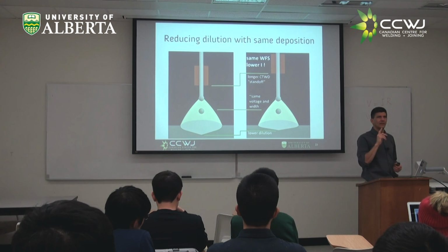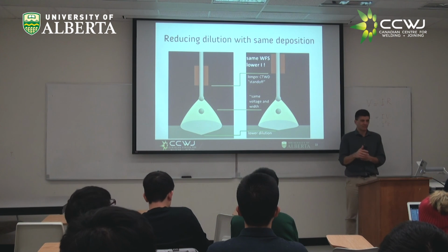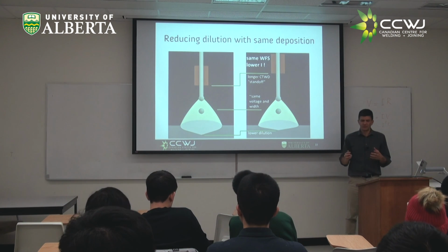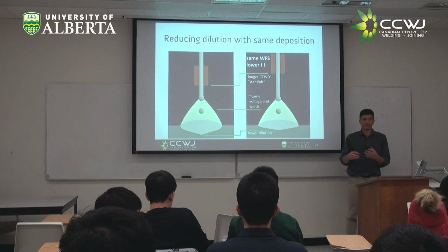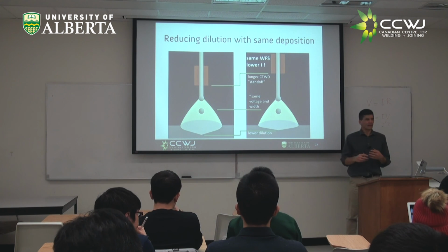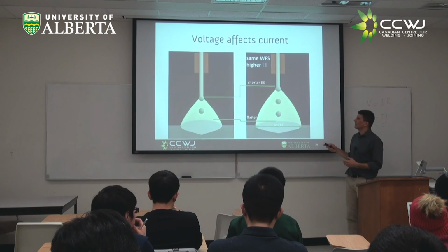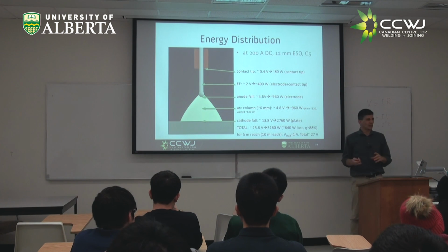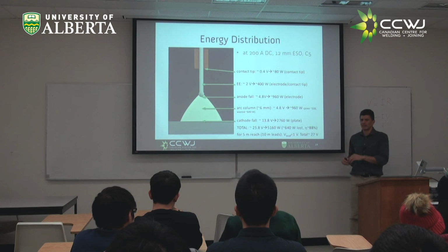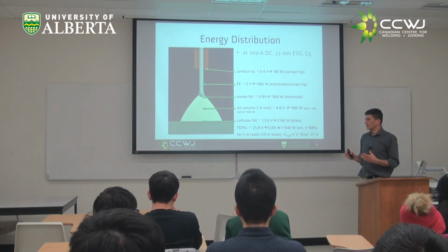Okay, so we have a few more minutes, and I want to get the next topic started. As we discuss this, this is just so amazing. We talked about the plasma arc, and the voltage associated with it because of non-local thermodynamic equilibrium, whatever it is. But that gives us an anode fall and a cathode fall. And now you start to see how there's a power associated with different parts of the weld. You started to see also what happens in the leads, how they affect pulsing or not, and whether they're long or short.